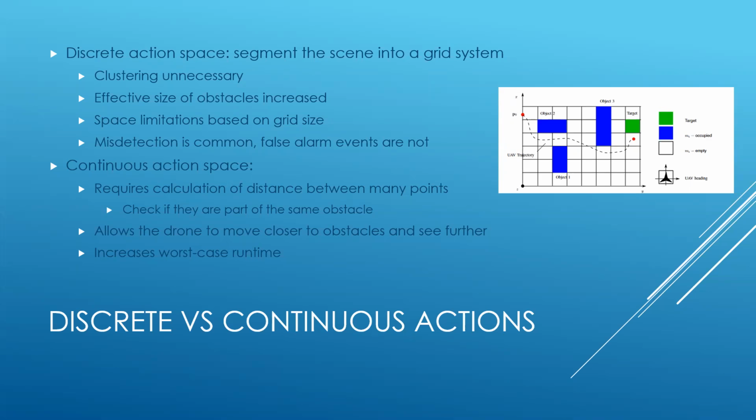In the example image, some of the obstacles are found along the path to the destination in a discrete action space. The width of each square within the action space is identical and corresponds to the warning margin associated with this algorithm. The obstacles in the scene are likely not perfectly rectangular with that specific width, but they are detected as such by the pathing algorithm in a discrete action space.